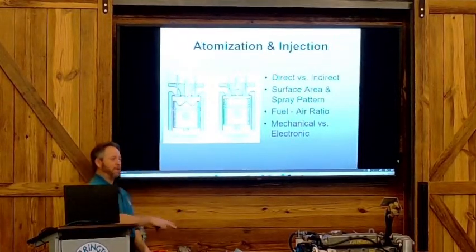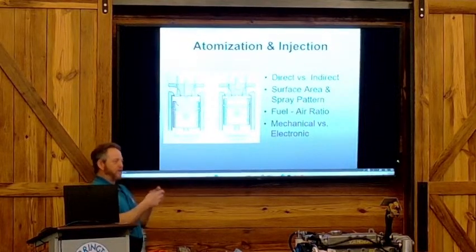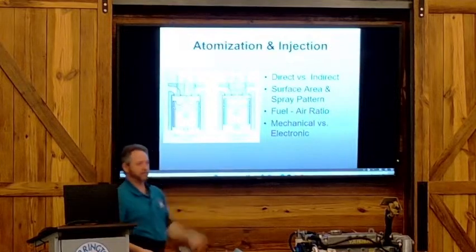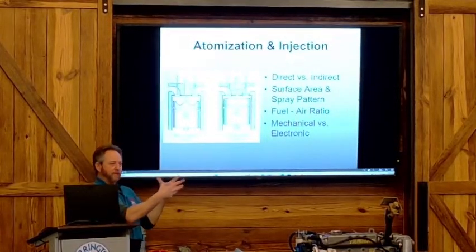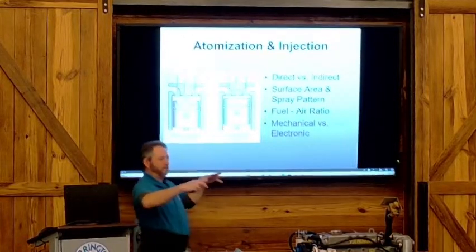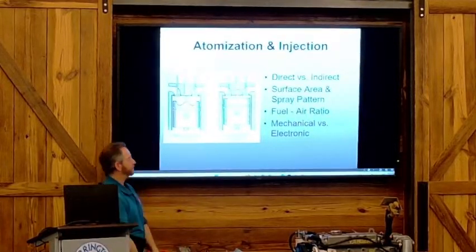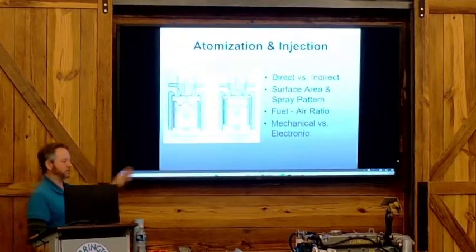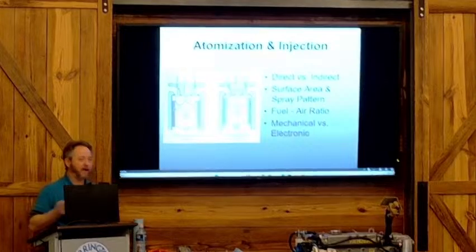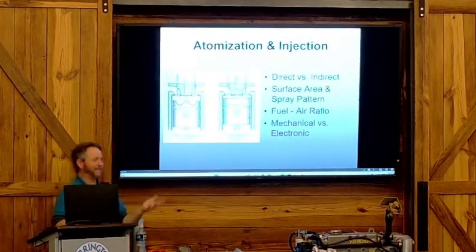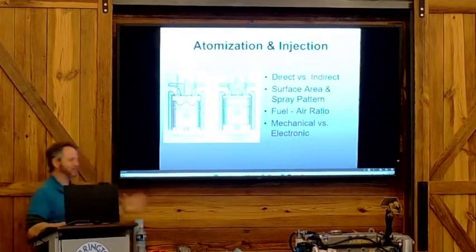So when we spray the fuel in, the temperature is actually hotter in that little cup than it is on top of the piston. The fire starts in that pre-combustion chamber, then blows out, fills the space, and forces the piston down. A lot of times on engines with pre-combustion chambers, you hear an injector knock. You all probably don't notice it, but it's a little extra clack that happens when the cylinder fires.